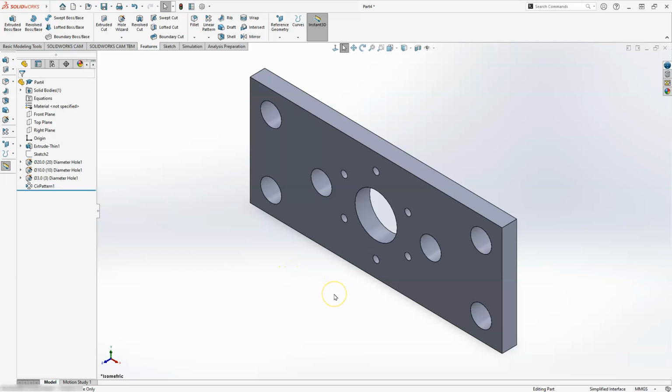Okay, so hopefully you enjoyed watching this video. This was a good example that I can find. Oh, I did forget one other thing, and I'm so sorry about that. Let's go ahead and put the fillets on here. So let's go with the fillet command. And then we do have 4 fillets on here, and they have a radius of 10, right?